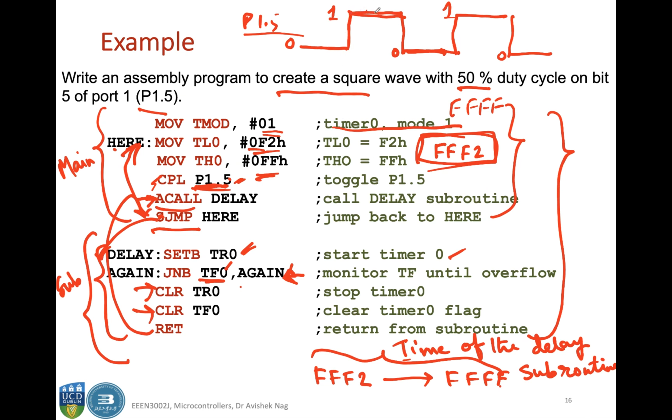So this is your just calculated time interval. This is 15.19 microseconds, and this is for half the pulse. This is also 15.19 microseconds, and this is the total pulse width, one entire cycle of this square wave.